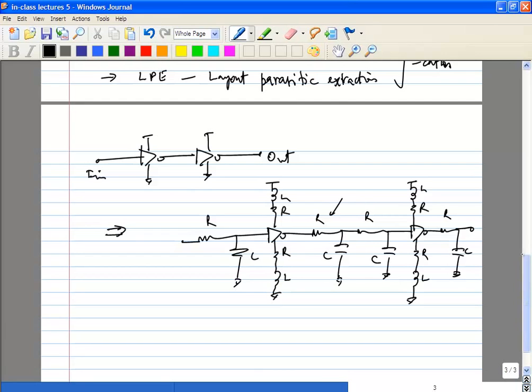Capacitance level extraction will tell you things like, the slope of your signal will get degraded if you add more capacitance, because your circuit will not be able to slew if you take an inverter. If you do RC extraction, it will tell you whether there are bandwidth limitations. If you are trying to send a signal along a certain line, is it too resistive or too capacitive? There's going to be an RC bandwidth. Again, there are circuits where inductance is very critical.